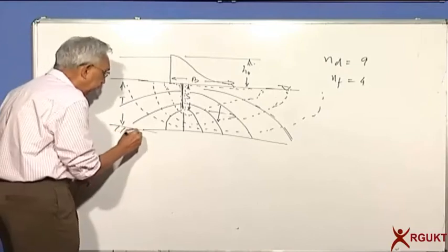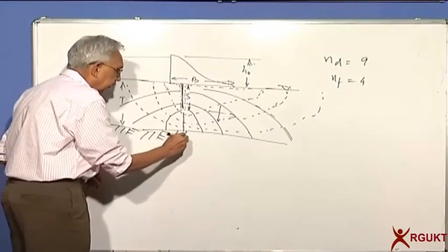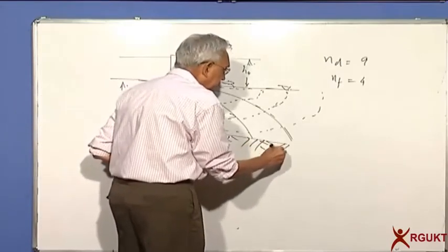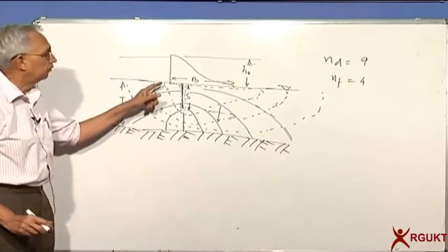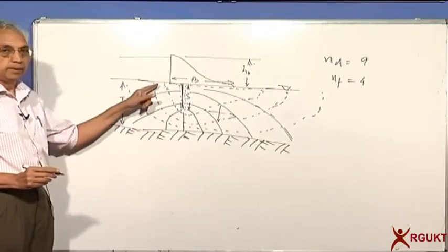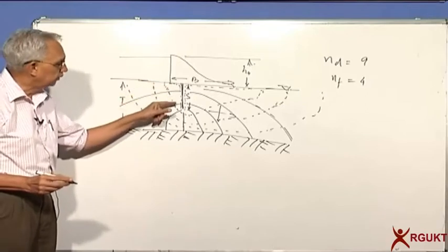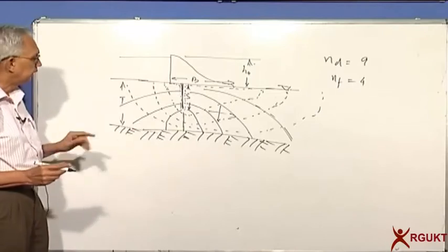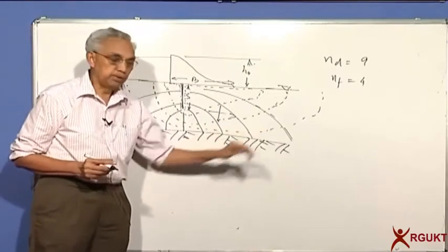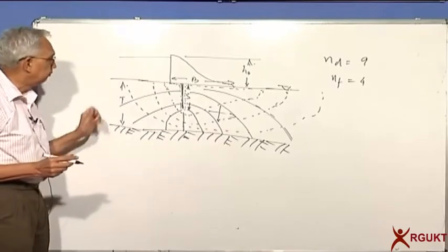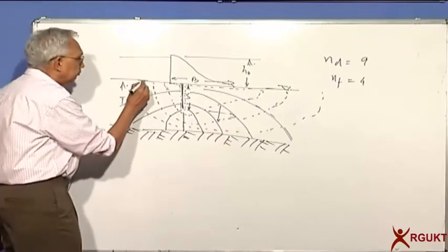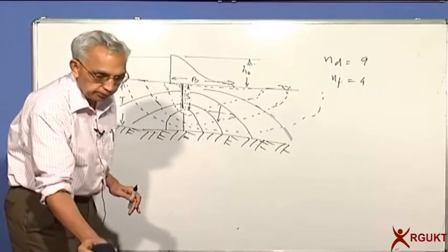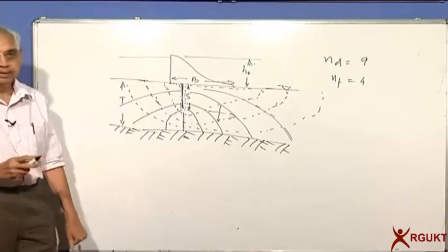All that we do here is make sure we satisfy all the boundary conditions and the main characteristics of the flow nets, which means the flow line will start from the upstream boundary orthogonally, will go along the sheet pile for the shortest one, and then go along the bottom of the weir, and the longest path will be along the bottom of the pervious stratum, and all others will be intermediate. Maybe something like here I can do that. And the equipotential lines are then drawn to make sure each element is approximately a square.